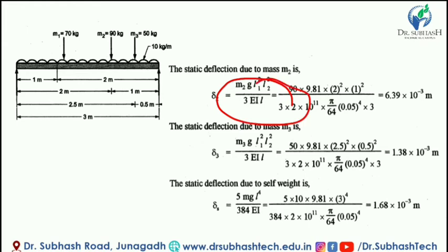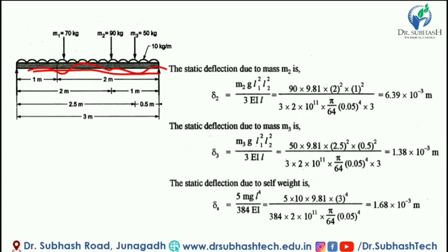So how is delta found? The value of delta is found with the help of the simply supported beam deflection equation. The shaft is considered as a simply supported beam, the bearings support the shaft and are considered as simple supports, and the self weight of the shaft is considered as a distributed load, and the rotor weight or mass given is considered as a point load.